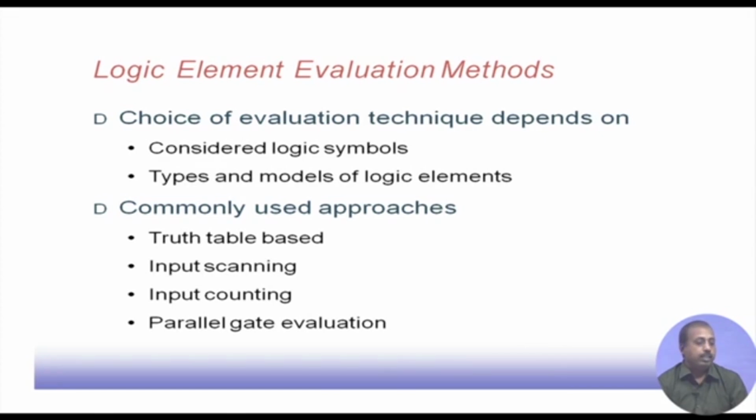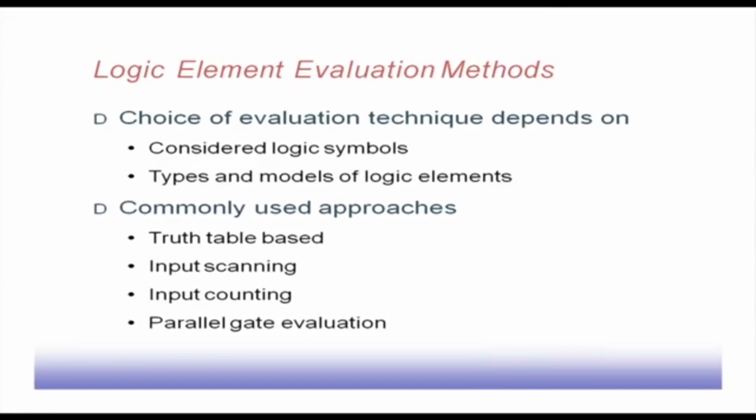Like if all are logic gates and flip flops, then we may be following some simple evaluation strategy, like using AND or NAND NOR functions. If it is driven by some other bus resolution function at some point of time, maybe we have to use that. So, commonly used techniques are the truth table based approach, input scanning approach, input counting approach, and parallel gate evaluation approach. So, we will see them one by one.